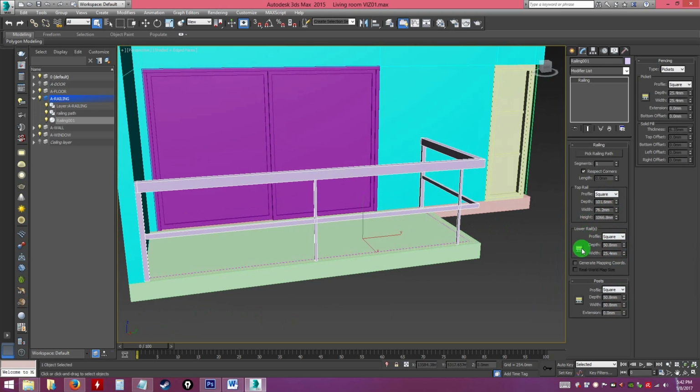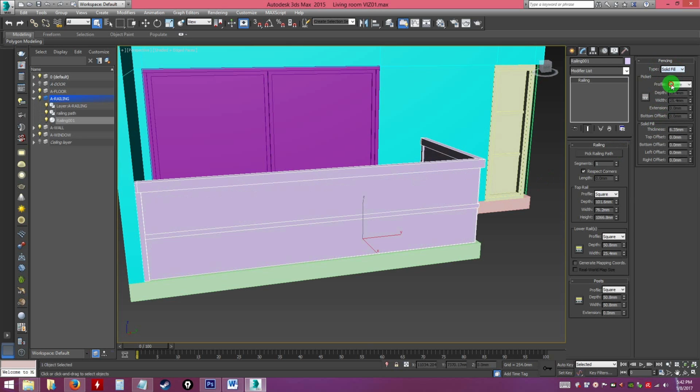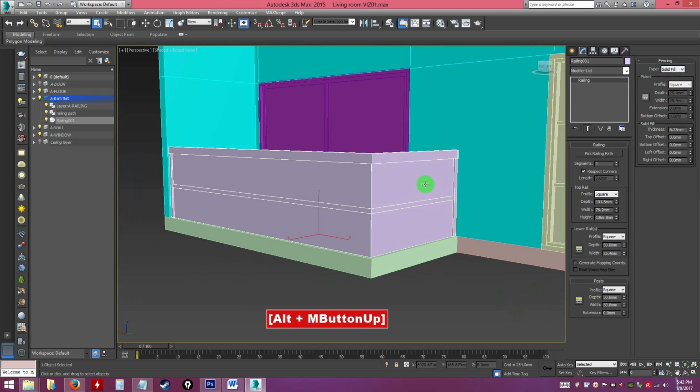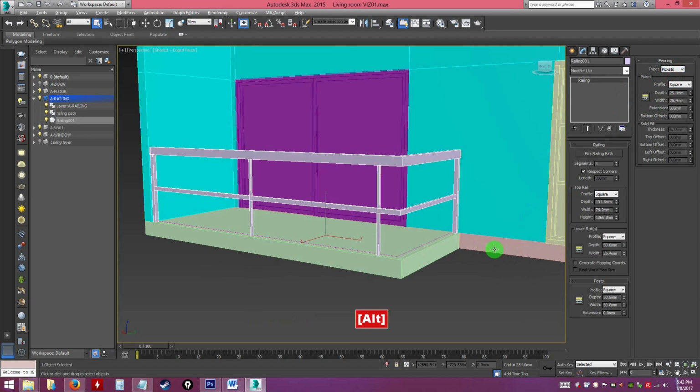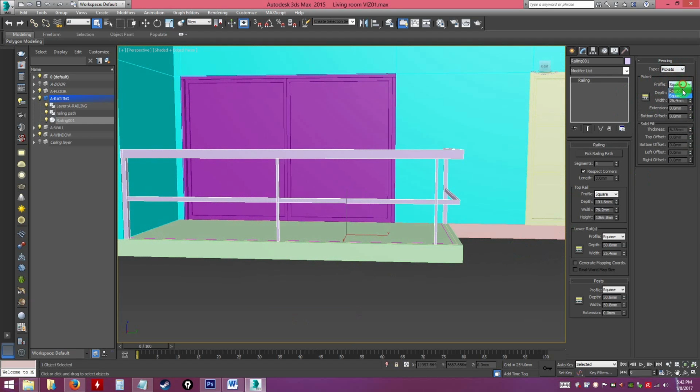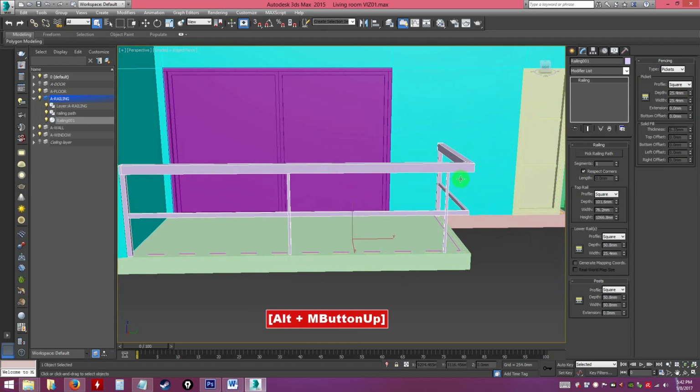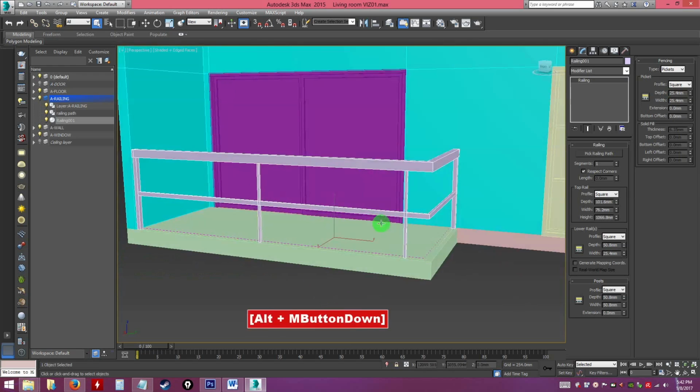And I will put, let's say I want more, this is the fencing, put that solid. So if solid means I can make this part here glass, right? But I don't want a glass, just want to have it picket. Picket square, you can have it round, square. All right, now I want to have more pickets because this is a bit dangerous. So what you can do, you can also adjust the dimension here, the depth, all right, things like that.